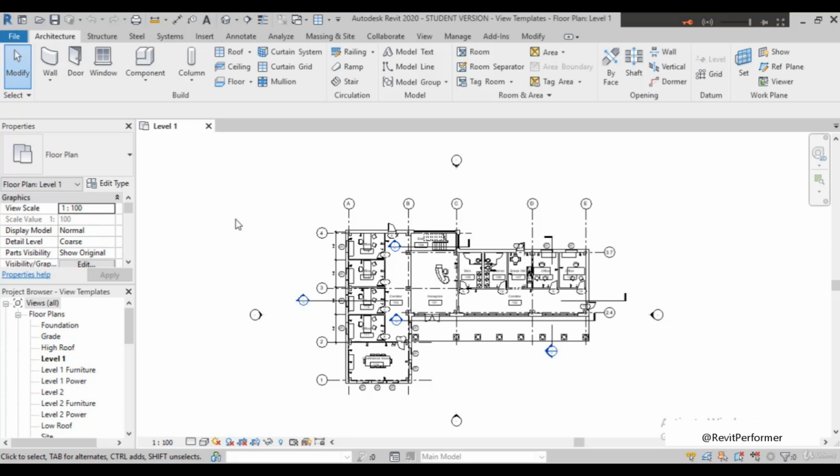It's certainly possible to go into each of the other plans and replicate the same settings, but it soon takes a lot of time, and I probably wouldn't enjoy it very much. So Revit offers a feature called view templates. It is a very simple tool which captures all of the setting data applied to a particular view, gives it a name, takes a collection, and applies it to other similar views.